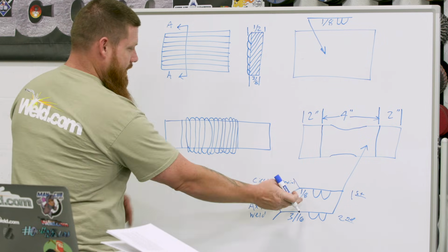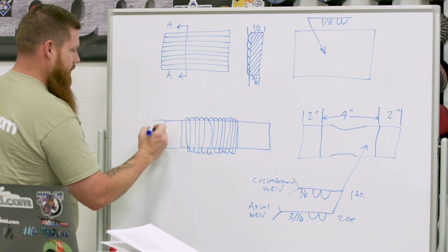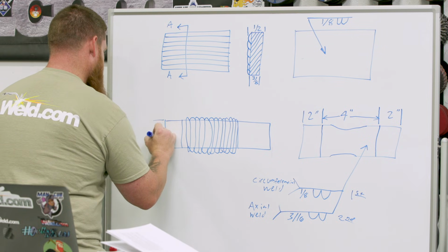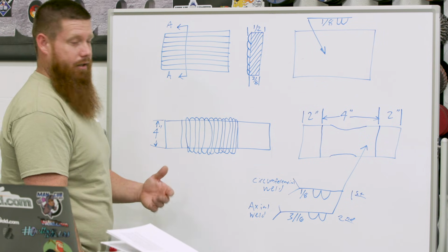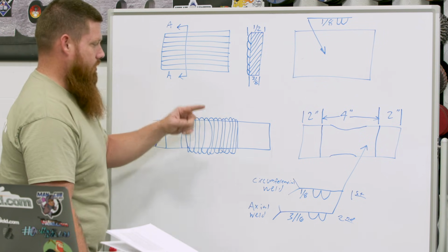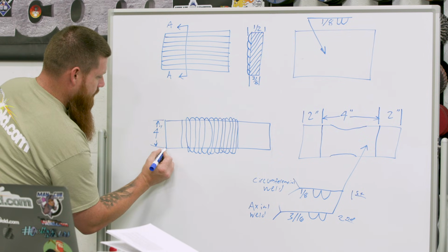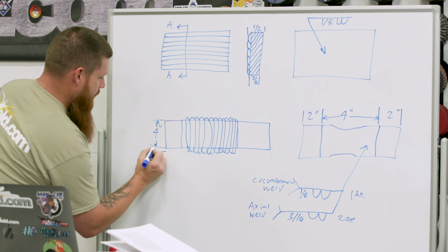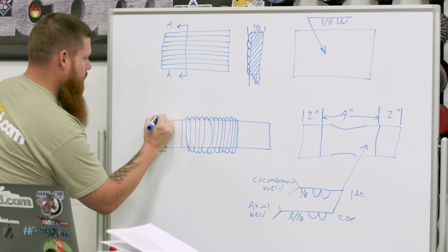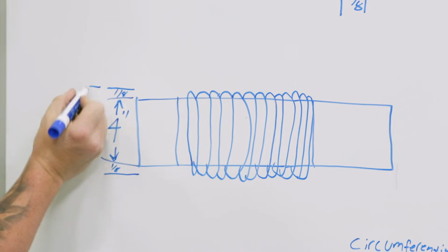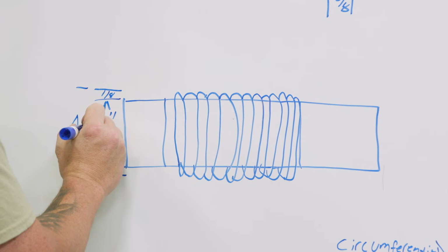So now we have our 1/8 inch, right? So let's say we have a 4-inch material, or a 4-inch outside diameter piece of material or shaft. What are we up to now? Not 4 1/8, right? We have 4 1/4 because we did 1/8 inch circumferential all the way around. So we have to add that 1/8 inch on both sides. Out here we're up to an additional 1/8, up here an additional 1/8. So overall, I've increased 1/4 of an inch. So now I'm up to 4 1/4.